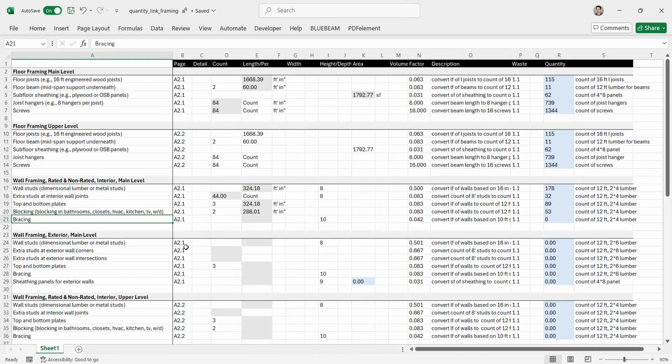Okay, and then the other line is bracing. Bracing refers to the diagonals that you put to increase the resistance against lateral forces, including wind during the construction and after that. And that bracing, you can assume it is done every 10 feet up to every 20 feet of the linear distance of your walls.